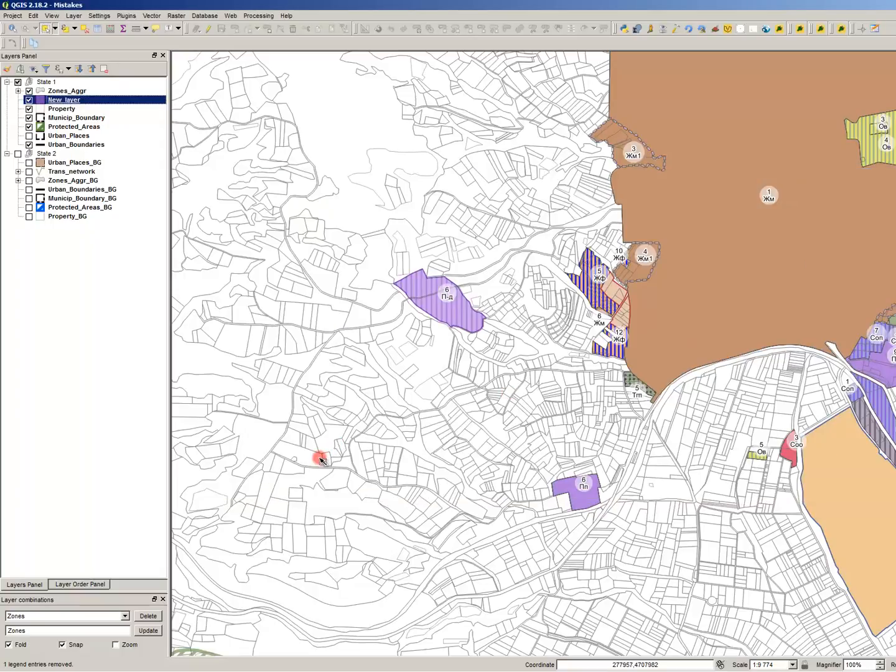Why do I suggest that? In QGIS, maybe column names can sometimes have Latin or Bulgarian names, but in other programs when exporting it may result in serious problems. So don't experiment naming your layers or columns in Bulgarian.